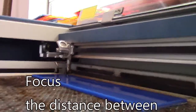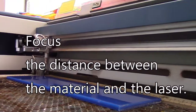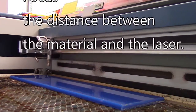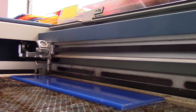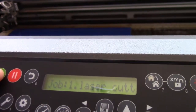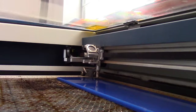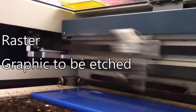Another important thing you need to know is focus, which is the distance of the laser from the material. So in this situation, you can see that I'm raising and lowering the cutting bed. This allows the laser to increase and decrease its intensity for different materials. Once we've done that, we've got our job here. We press go, lower the laser cutter lid as it autofocuses for size and begins to raster the image.